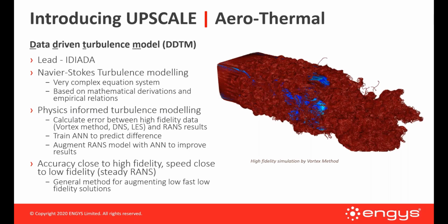accurate in many conditions. So the idea simply here is, let's look at the results we get from the RANS modeling, let's look at the time average results we get from the DES modeling, and let's find a way to get that neural network to increase the accuracy of the RANS model so that it approaches that of the DES. I.e. we're trying to correct the error in the RANS to make it better.